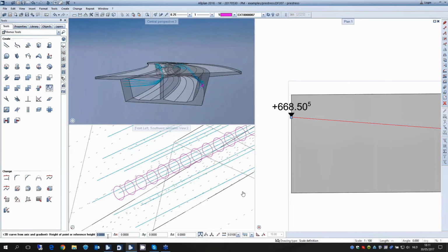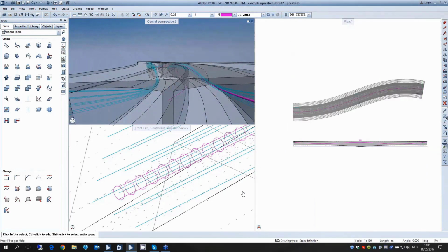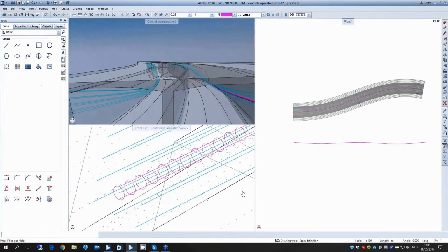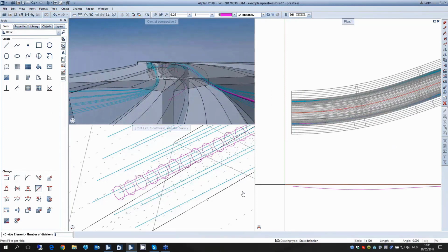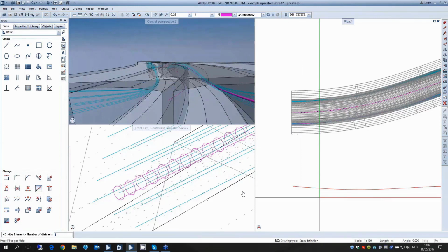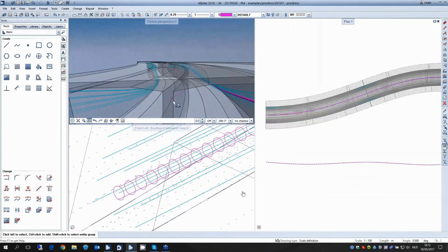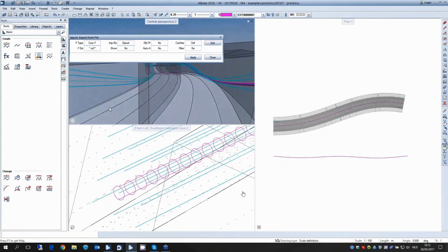So what we're doing now is that we've identified that curvature. We're going to export this to a file on disk. But before we can do that, we're going to want to discretize it into individual points. One of the benefits of ALLPLAN typically is that all of your shapes, your splines, your curves, those are not approximations or polylines. Those are actually 3D curves that are controlled by formulas. So when we do volume calculations, area calculations, length calculations, we're using calculus to integrate those. We're not just simply doing a simple summation.